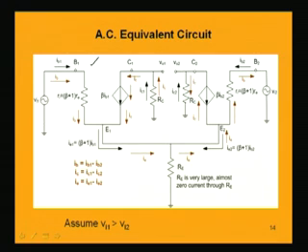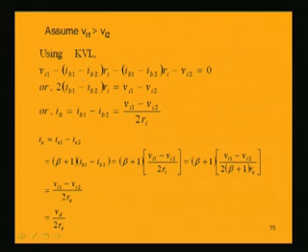We need to apply Kirchhoff's voltage law in this loop, comprising VI1 and VI2 and then ground. The two grounds are combined, so we basically have a loop, and we need to find the drops in this direction. We start from this point, minus to plus, which is a rising voltage: VI1 minus this drop IB into RI, minus this drop IB into RI again, minus VI2 is equal to 0. What is IB? IB1 minus IB2. So VI1 minus (IB1 minus IB2) into RI minus (IB1 minus IB2) into RI minus VI2 is equal to 0.